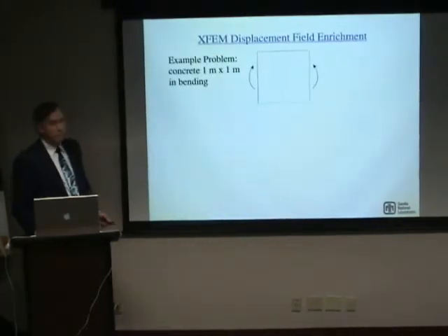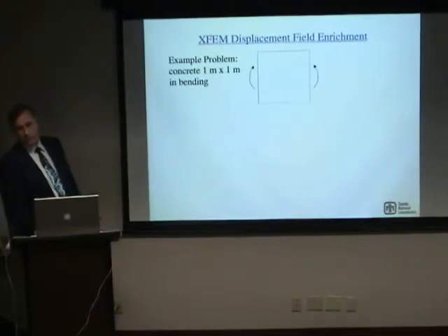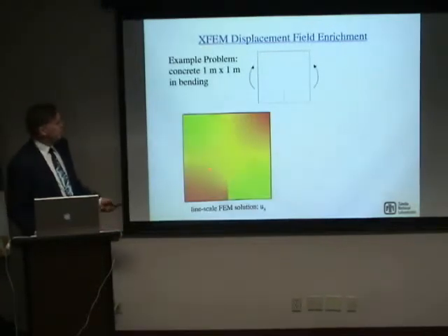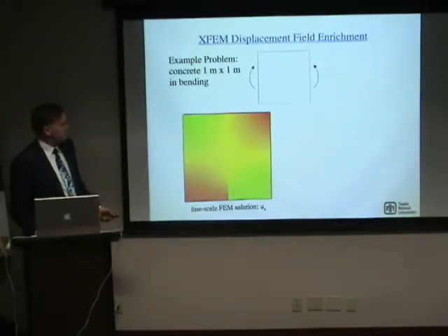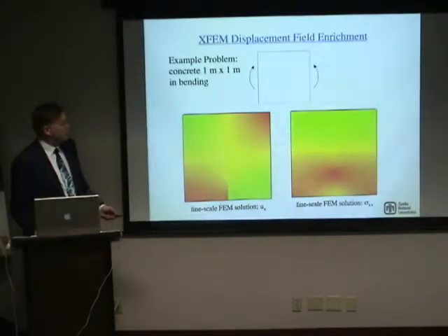So I wanted to first introduce, very quickly, reiterate the idea of how we're doing this. So this shows a fine scale solution for U sub x. So again, this is with the 80 by 81 mesh. This shows a solution for sigma x that you've seen before. And the way that I noted earlier that we're able to obtain this type of response in the XFEM is by incorporating the enrichment terms.